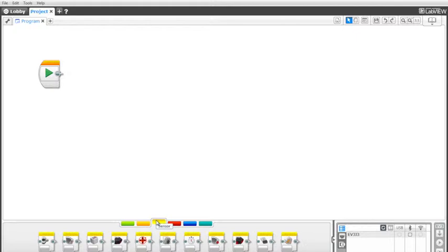So in the sensor programming palette, you will see various sensors. We'll talk about a few of them, not all of them. So first one, the color sensor. Okay, so color sensor can detect colors or detect the light reflection, or we'll learn later, it can also detect ambient light. So basically, if you pull up the color sensor, here you need to specify which port the color sensor is connected to. Choose one from 1, 2, 3, 4, whichever you connect to your robot.